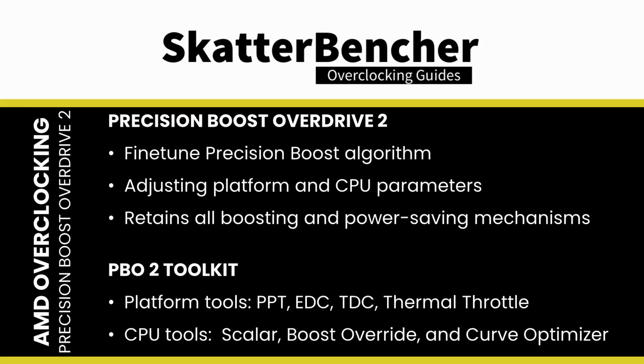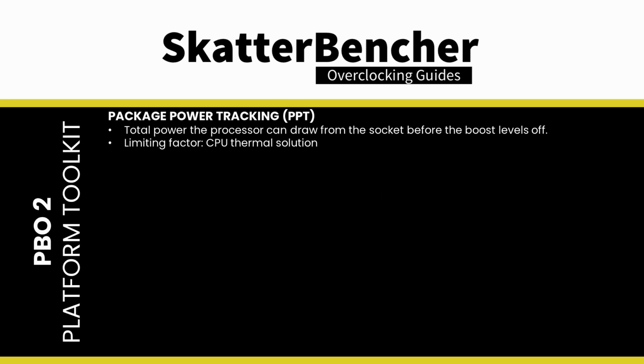The Precision Boost Overdrive 2 toolkit for Zen 4 is identical to the toolkit of Zen 3. So anyone who's already familiar with PBO2 can skip this part of the video. If you're not, I'll gladly reiterate how everything fits together. There are a total of 7 tools available to tune the Precision Boost 2 algorithm: 4 platform configuration tools and 3 CPU configuration tools.